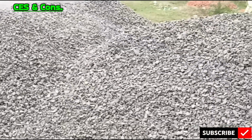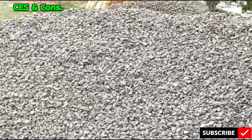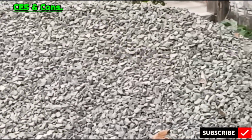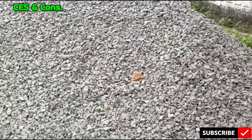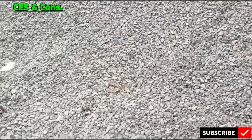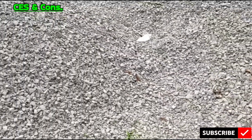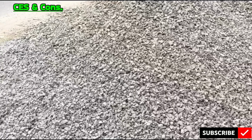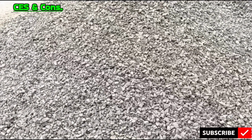It should be hard, durable and free from impurities such as clay, silt and organic matter. Water absorption should be less than or equal to 2% by mass. Crushing value should be less than or equal to 30% for ordinary concrete and less than or equal to 45% for non-structural work. Impact value should be less than or equal to 30% for wearing surface and less than or equal to 45% for other concrete. Angular aggregates are preferred for better interlocking.